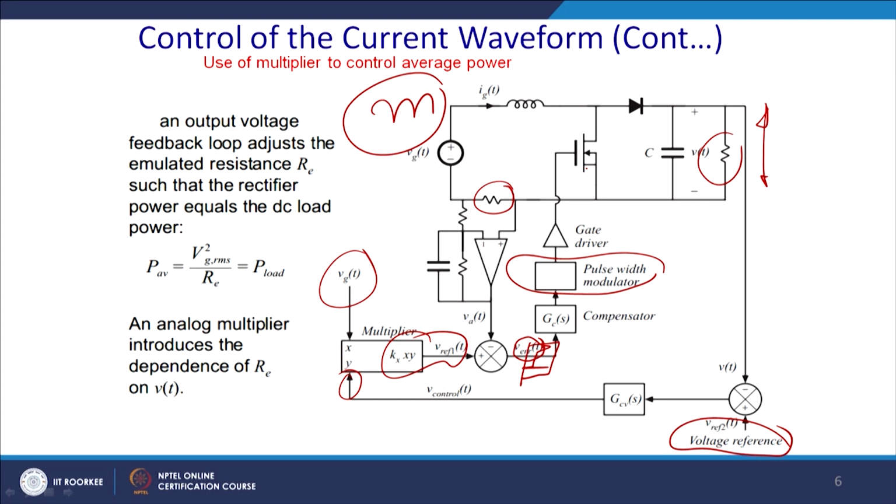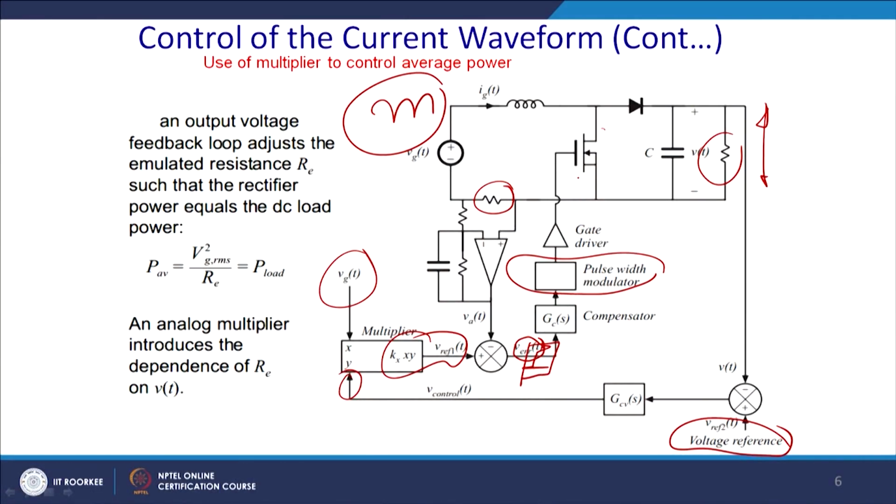If the power rating is low, within 500 watts or so, the solution comes with MOSFETs, and if the power rating is higher, then we require an IGBT solution. If you have a huge power rating, more than 10 kilowatts, then we may require to operate this boost converter in parallel, and there are many topologies like the interleaved boost converter.